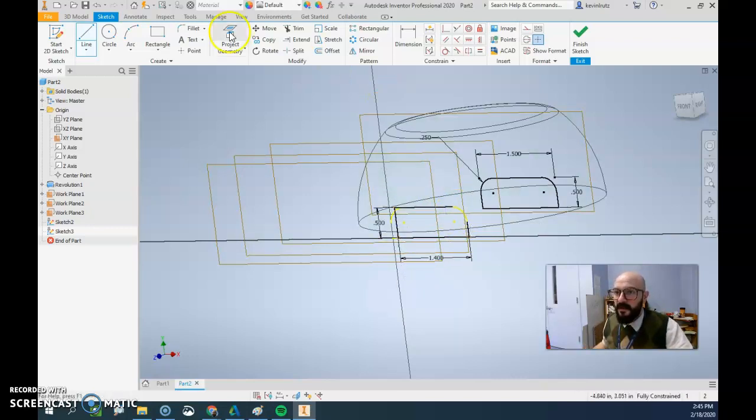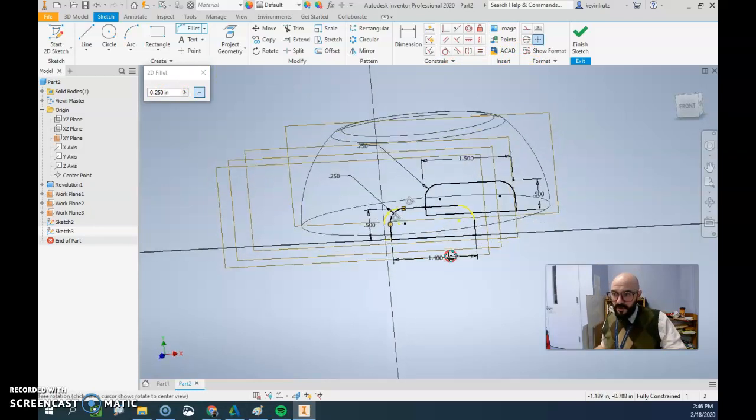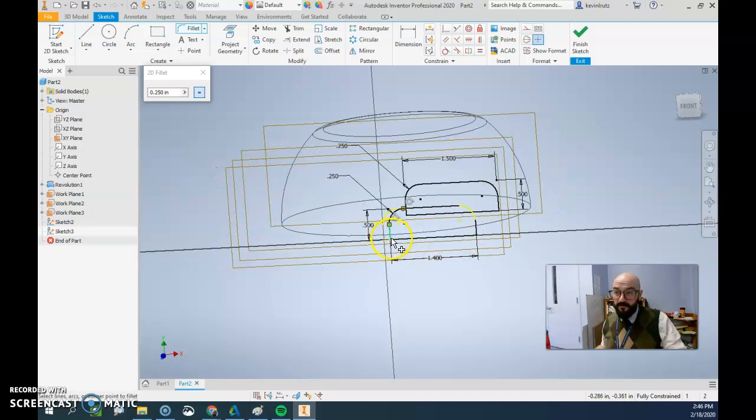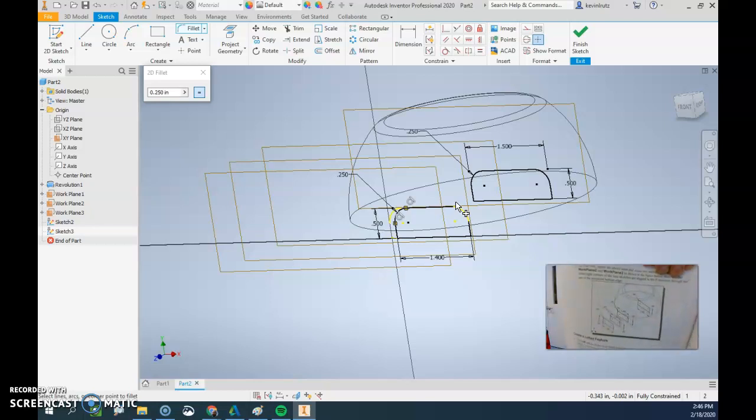Good. We're going to connect it there. Now we're going to use that fillet here and here for 0.5. Cool. And we want to make sure that we shrink it. We want to remove 0.1 inches this way. So now we're going to move on and do our next steps. I'm going to just put a picture real close. Hopefully you can see it. So we're doing the same thing, except the next work plane is going to have a width of 1.2. Everything else the same. And the furthest plane is going to be 1.35. Do that now.